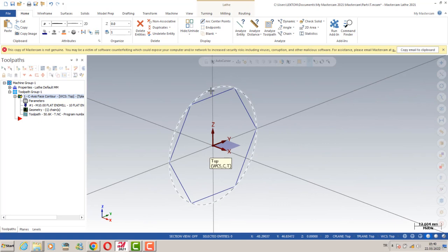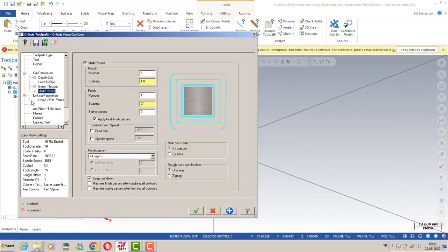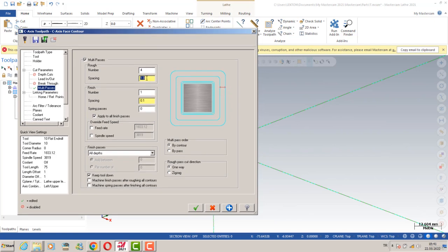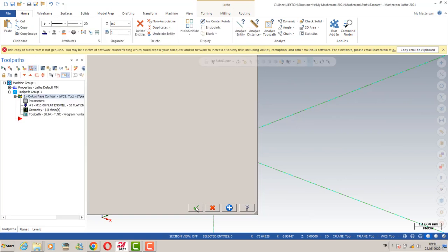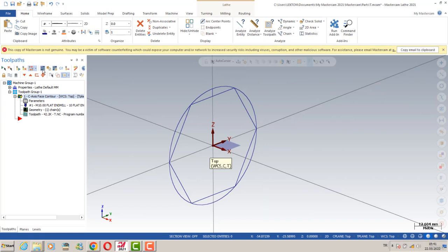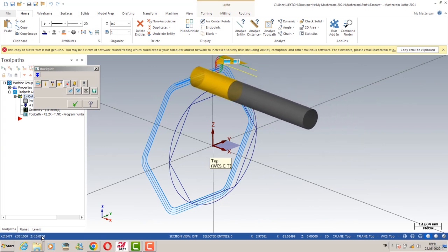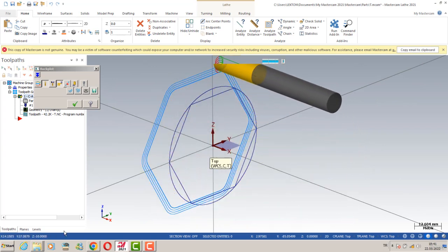So after that, I can turn to top again, or isometric perspective. So this is my stock, and then we can turn to multi-passes. That's gonna turn to 5 millimeters. According to my analysis, I just need to write here 4 multiplied by 1, and that is gonna be enough for us. So this is my final depth options. Okay, this is -10, and we're gonna cut all my product by using our tool helix.